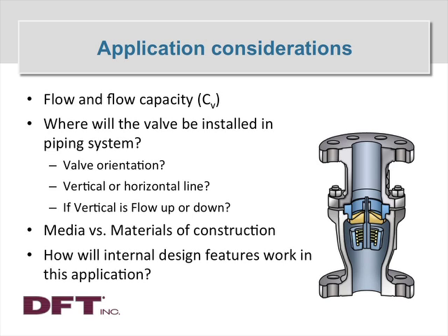Will there be solids or whatever that might have to pass through this valve, and will they be able to get through the valve given the design of the internals of the valve? Finally, will the valve design cause water hammer in this application? That is a very real possibility with vertical lines. Water hammer is a whole other subject for another webinar, but the causes need to be considered when thinking about the application and the style of valve that you're going to be choosing.